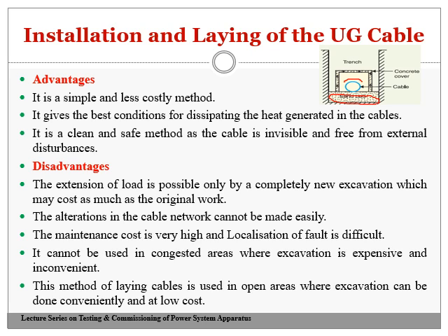Now let us come to the disadvantages. The extension of a load is possible only by a completely new excavation, which may cost as much as the original work. Suppose a new extension is required, and I want to lay a new cable. At the time the extension of the cable is required, we have to excavate a new trench. It becomes just like the original work.